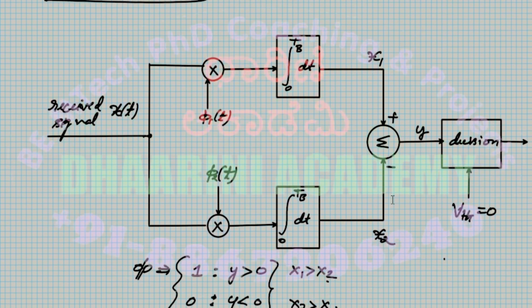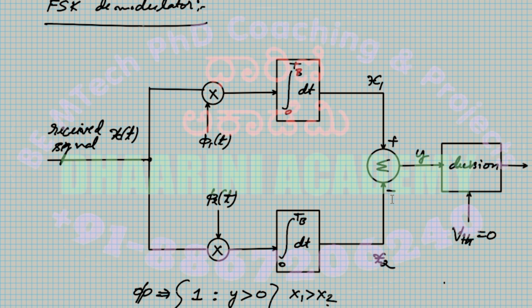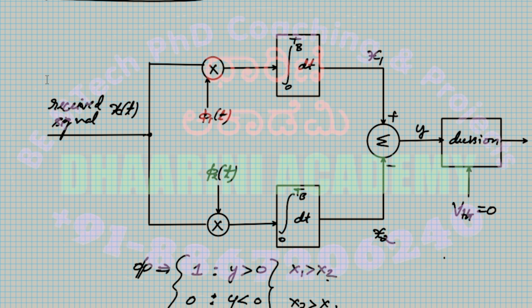Okay. Similarly, demodulation is also pretty much similar. Again, this demodulator is assumed to know the frequency. It's a coherent detector, so phi1 and phi2 are known. Once you receive the signal, split it into two parts, right? One part gets multiplied with phi1, the other part gets multiplied with phi2. If you have the signal which consists of S1, the phi1 branch integral will give you an x1. At the same time, the other part is going to give you x2. So what we do, we subtract x1 minus x2, which will be considered as y.